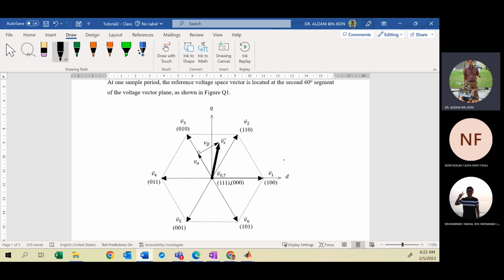So the equation must be in terms of switching state. So remember how to derive the equations. You need to support with a suitable diagram. So remember you have the inverter. You need to obtain the expression of any phase voltage. From that, you do this substitution, and finally you can get the equation in terms of the state. So you have 6 active vectors and 2 zero vectors, where the zero vectors are located at the origin.